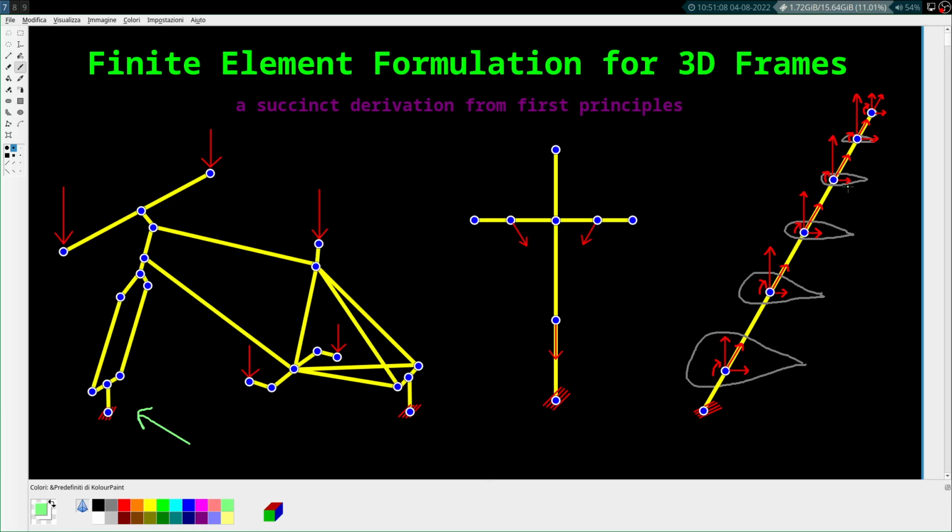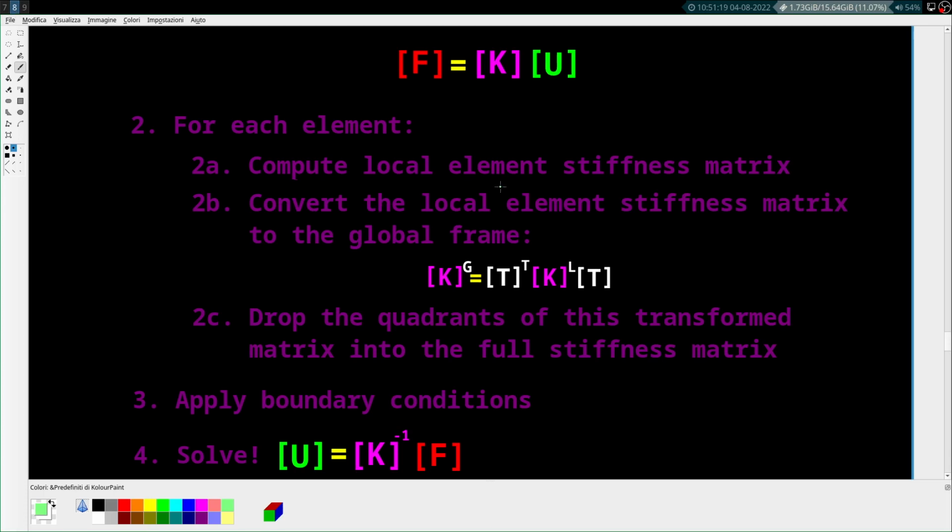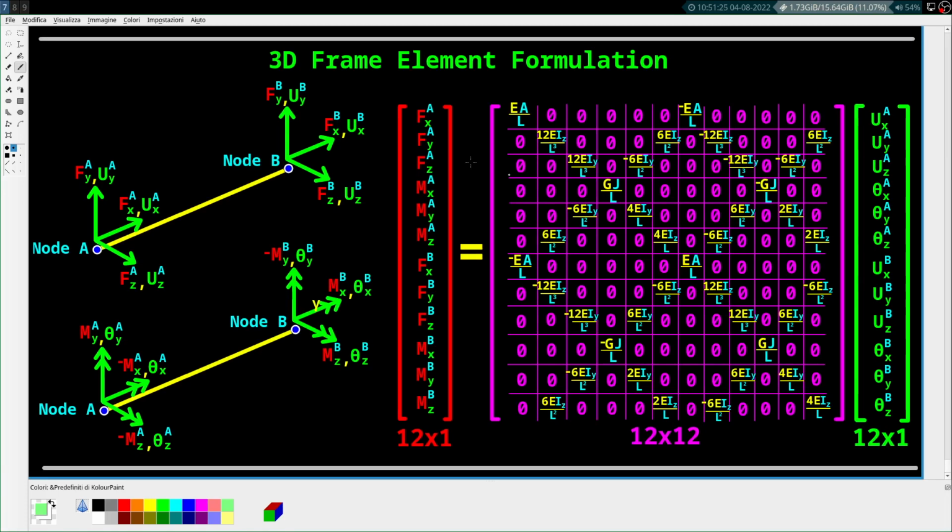That is this, right? And this is purely geometric and material, right? And there's also the vector v we talked about, right? You have to know that as well. But you're computing this local element stiffness matrix. It's a very straightforward thing to do. Right? Literally just plugging in numbers in this 12 by 12.